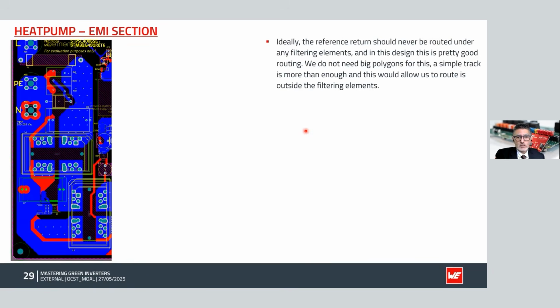A couple of quick slides on this specifically with regards to layout and tracking. On the EMI section side of things, a key recommendation for us is not to place any tracking under the filter components so that you do not get any capacitive coupling across those common mode chokes. You can see here there's daylight across the common mode chokes so that there is an optimization of the impedance or common mode rejection across that common mode choke.